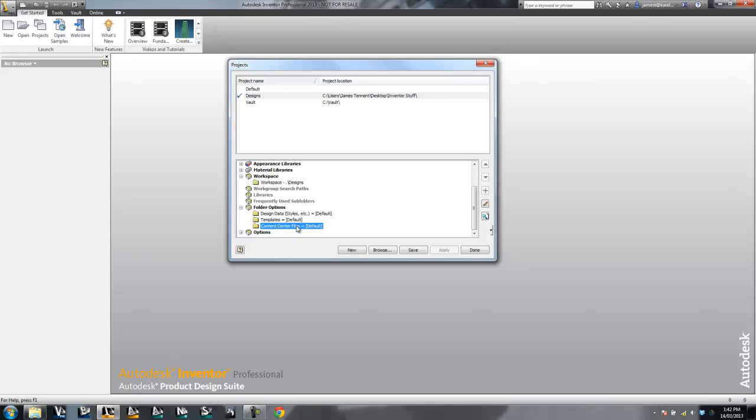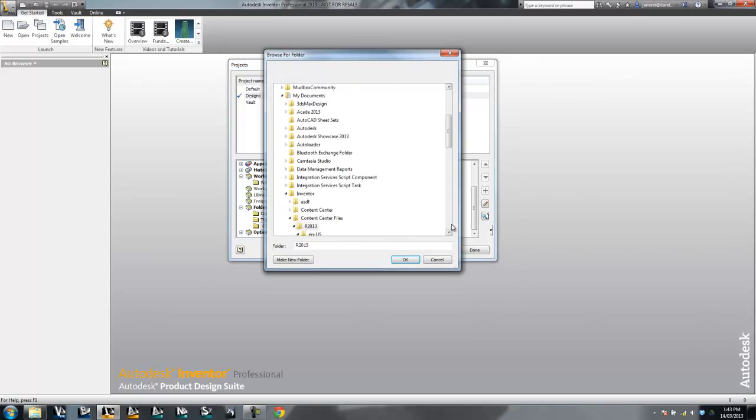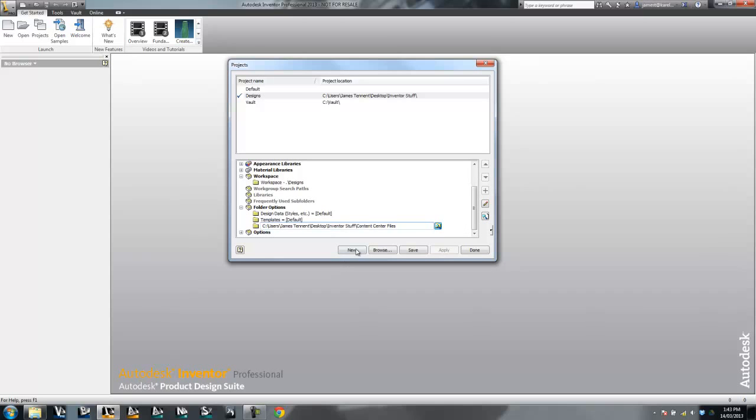You could fix the problem by copy pasting the bolt into your location, the same as on my location. However, it's just going to be a very cumbersome thing to do, to keep this Content Center folder identical on all machines. It's very, very important that you redirect this guy to being in a communal location. In fact, I have no idea why it wants to default to my documents. It shouldn't even allow you to go any further without doing this, because literally you'll save yourself hours of headaches if you just do this one mapping. And again, I know it's correct when it's just /Content Center files.